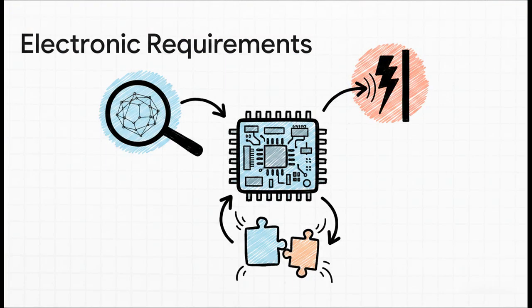If you are the one specifying materials for things like hybrid microcircuits, insulating packages, or high-voltage vacuum feed-throughs, well, these are your non-negotiable dials. You've got to start with that high-purity alumina, greater than 99.5%. You need an internal structure that is completely free of any conducting secondary phases to keep that dielectric loss super low. Plus, from a pure design standpoint, you have to carefully manage the CTE, the coefficient of thermal expansion. If you don't manage that mismatch, your ceramic is going to crack the second it's bonded to semiconductor metals that expand at different rates.